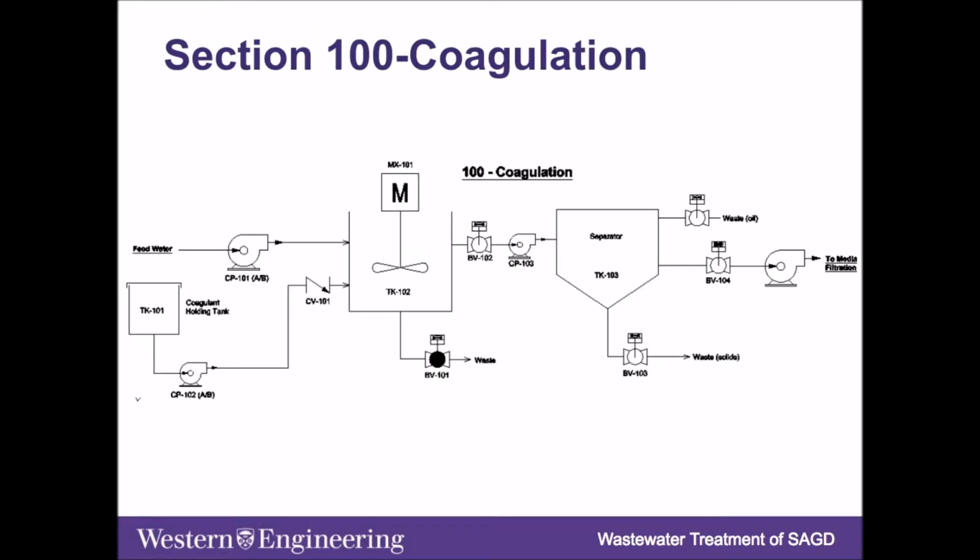Most of the non-emulsified oil is removed by the separator prior to the plant. Emulsified oil remains suspended in the wastewater. Chemical addition with high power mixing helps to break the charges or zeta potential between oil emulsions and particles. The particles can then sink to the bottom in the separator and the oil can float to the top. This will protect technologies downstream.